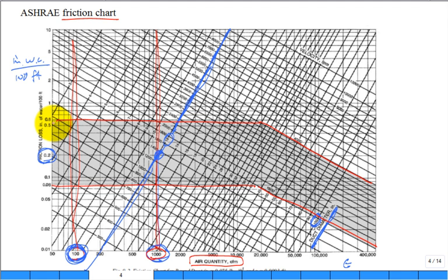And you can see that right away, that if I'm running a 12-inch diameter duct and all I'm doing is pushing through 300 CFM, that's really probably not economical. I should probably reduce it to maybe a 10-inch. That would move me up here. Could reduce it to an 8-inch. That would move me up here. More reasonable. If you get outside, you have too high of a loss. You're paying too much to push it.